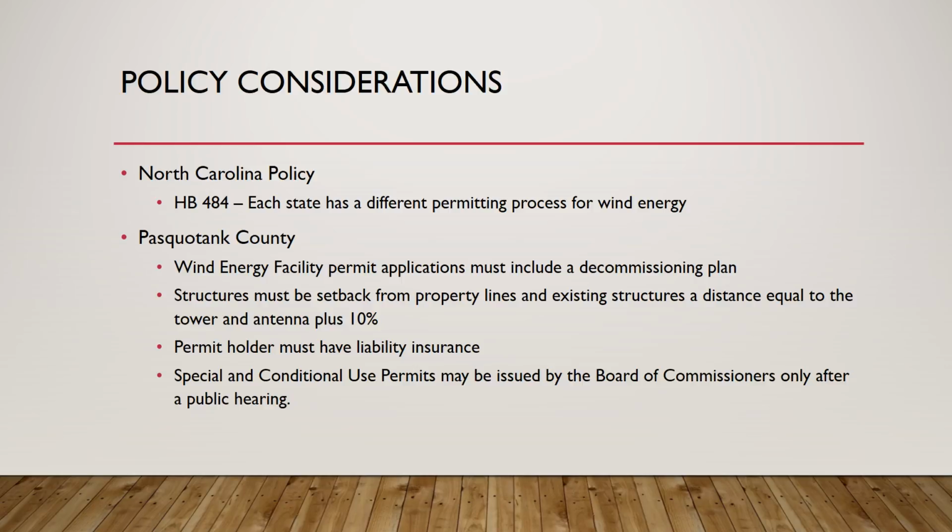Here in Pasquotank County, structures must be set back from property lines a distance equal to the tower plus the antenna, and another 10%. But here on this 5-acre land that we're using, we're going to install a tower that's 250 feet, which is the tallest tower you can use for a small wind facility in this county. And so we're still good. This doesn't violate any of those rules. So once again, this does not affect us.